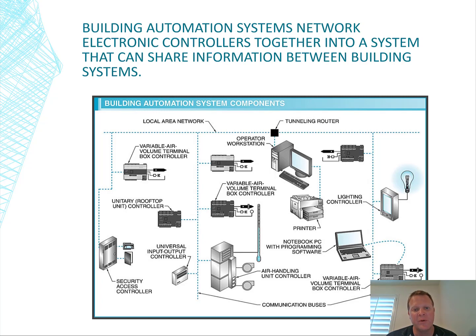And so no one is really walking out there saying, let's turn the lights off. We can turn the lights on and off, but it'll automatically do it if we leave and there's no motion sensor, right? Or when there's no motion inside the room and the lights are getting turned off, let's also reduce the heating or cooling to different set points automatically. It's just automatically doing some of these things. Not that the operator couldn't force it to happen, or manually do things, but the building automation system is taking over and making that entire thing run.